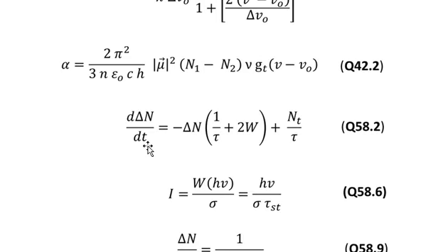This negative term, which is the spontaneous emission term, will make the rate of change of delta n with time decrease because of the negative sign present with the term minus 2W multiplied by delta n. The other term also has a negative sign, which we have combined here, that is (nt minus delta n) over tau. This is the spontaneous emission term in which tau is very large, so this term is actually very small.